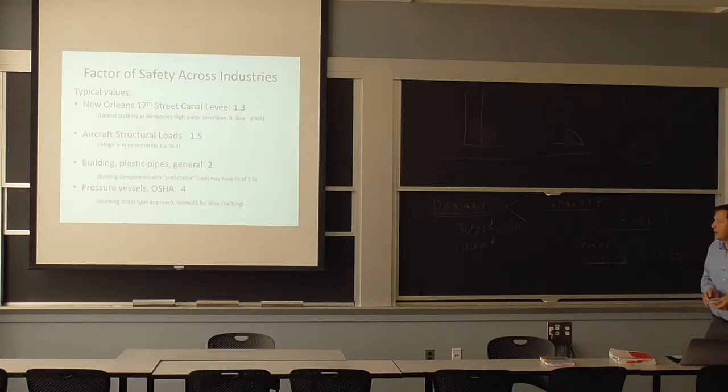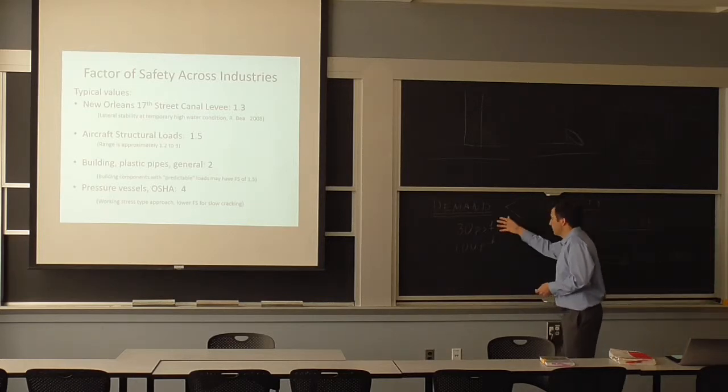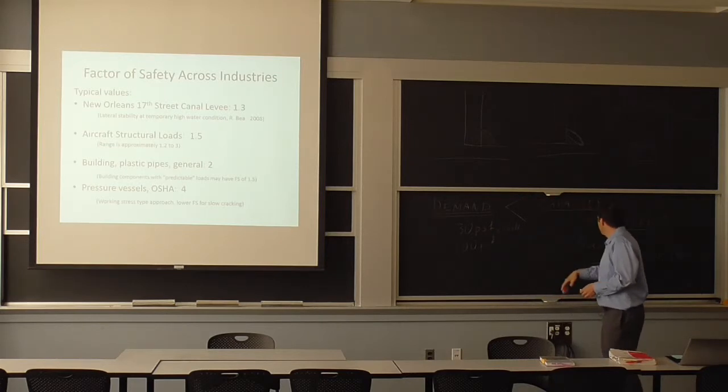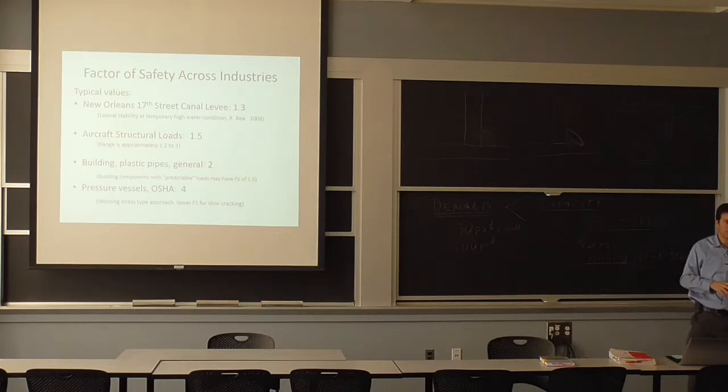If you're talking about a bridge, or we were talking about roofs a lot, a safety factor of 2 is very general, because they go through some math, but it's not absolute here, and it's not absolute based on, you know, for example, the Steel Joist Institute. It's not going to always meet that capacity. So they do put a significant safety factor.